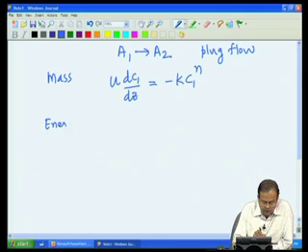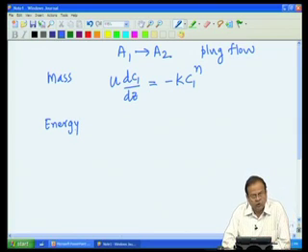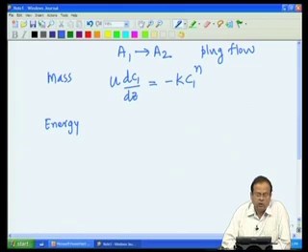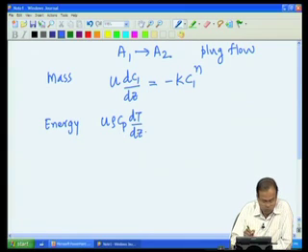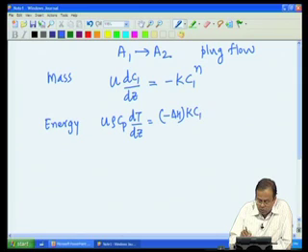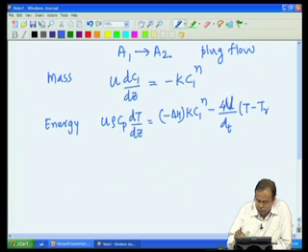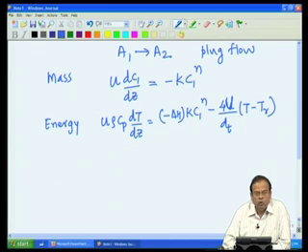Let us put in our energy balance now. We are carrying out an exothermic reaction and we are carrying it out by cooling it. So, we can hope that there is a safe operation, but let us see what happens. So, we write the energy balance: convective energy transport on the left hand side, the first term on the right hand side representing the heat generation, and the heat removal rate.